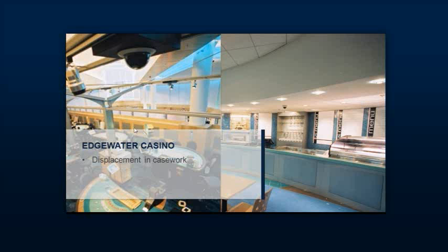The interior finish designer selected these wall-mounted diffusers, and they have a very, very large open pattern to them. Now, as a supplier of air movement, I can't really use that large of an opening. So there's most likely 3, perhaps 4 layers of perforation to make the uniform face velocity happen here.